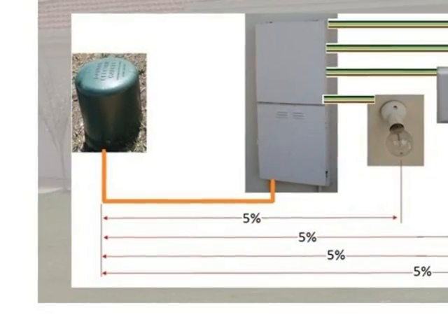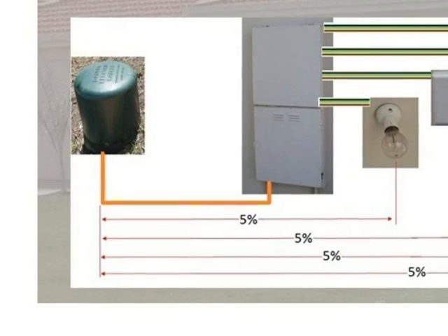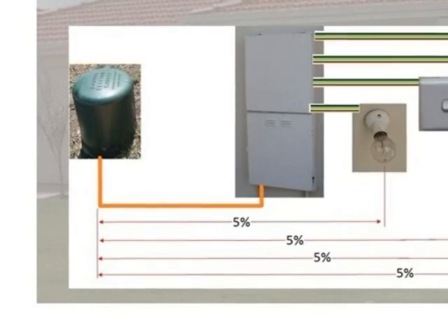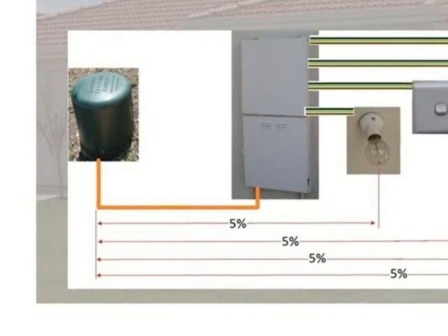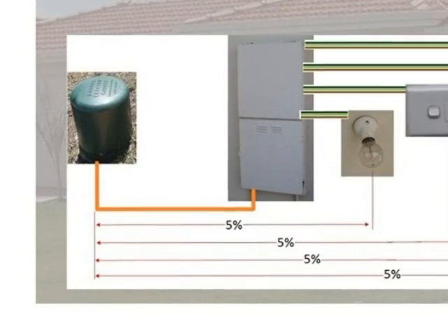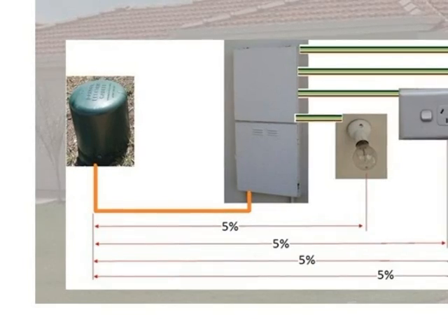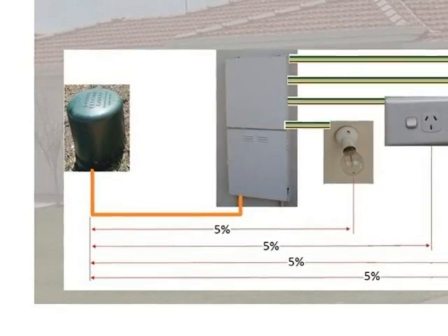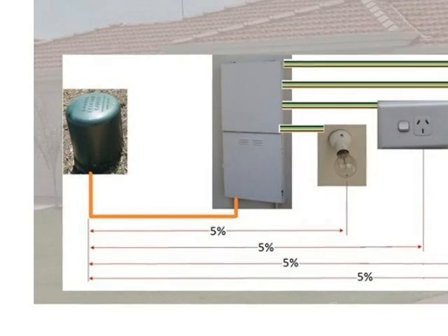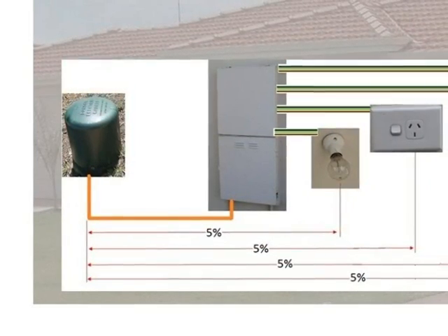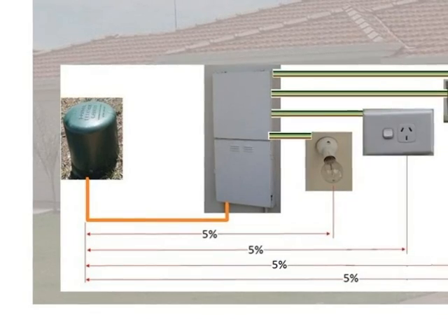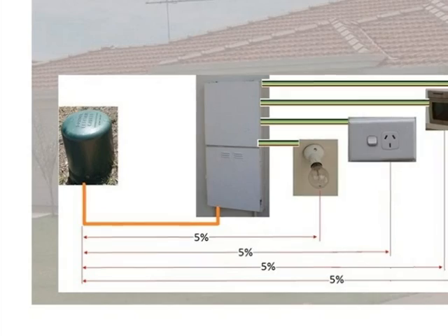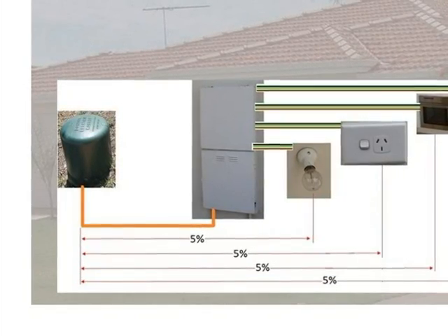Clause 3.6.2 of the AS/NZS 3000 wiring rules states that the cross-sectional area of every current carrying conductor shall be such that the voltage drop between the point of supply for the electrical installation and any point in that electrical installation shall not exceed 5% of the nominal voltage at the point of supply. So what that means is that it's simply from the point of supply, shown here in the graphic, say from the mini pillar